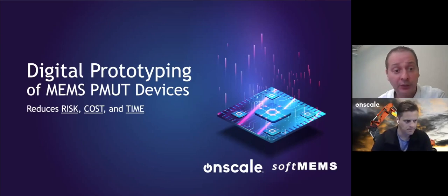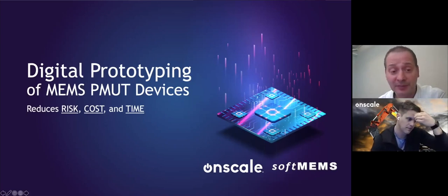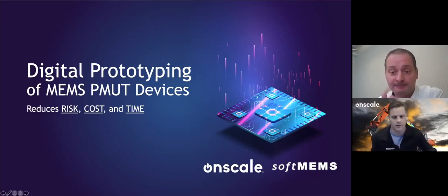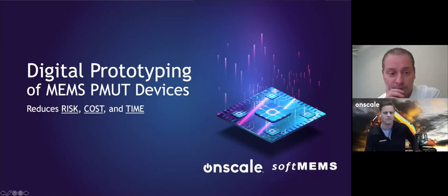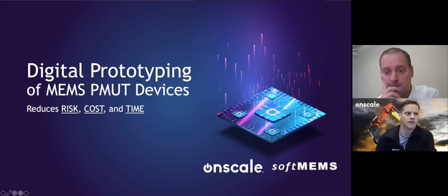Let's see. How accurate is your simulation compared to real values? So for example, frequency, capacitance, or sensitivity. Great question. We get that question every time we promote simulation. And I'll say it's as accurate as your input values. So think of a simulator as a calculator. It's going to give you 2 + 2 = 4 accurately, but you have to know what parameters to input.